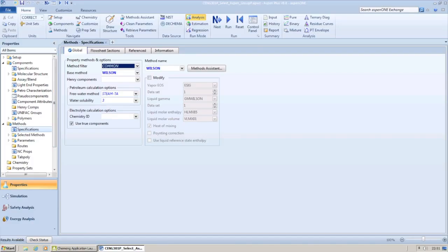When running our simulation in Aspen, we have to choose a global overall model as well as a specific localized model. This is done to represent the compositions, enthalpies, and model behaviors present accurately. The global model chosen was Wilson as opposed to NRTL and Peng-Robinson due to it having the lowest error in measuring those parameters. This was the case in multiple literature sources.